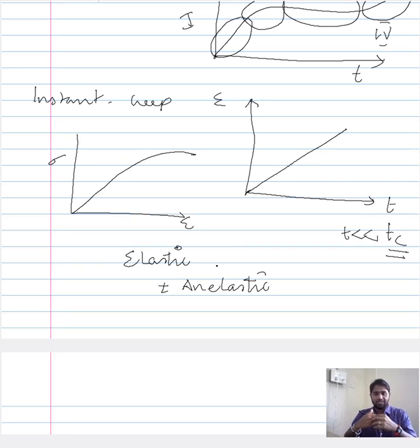The difference is that in elastic deformation, when you unload your material, the portion of the atoms which assume a reversible state will get back to its original state, thereby re-establishing the original form of the material at the given instant.